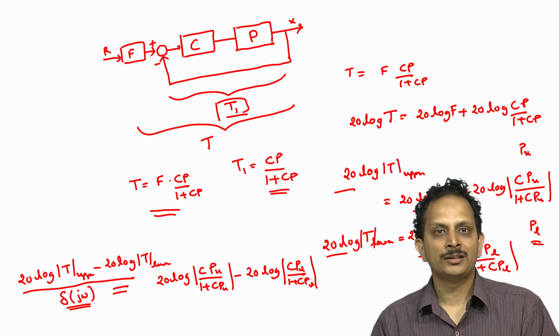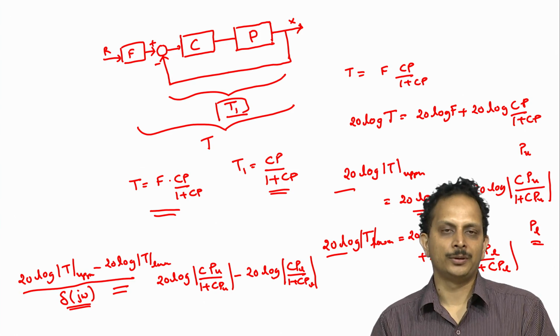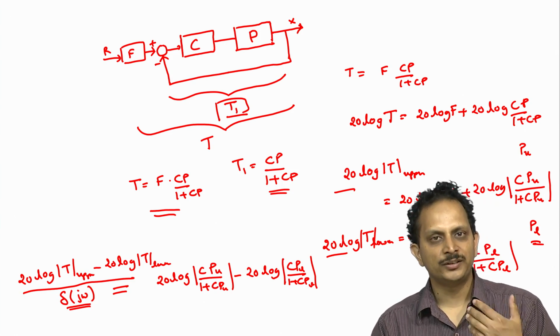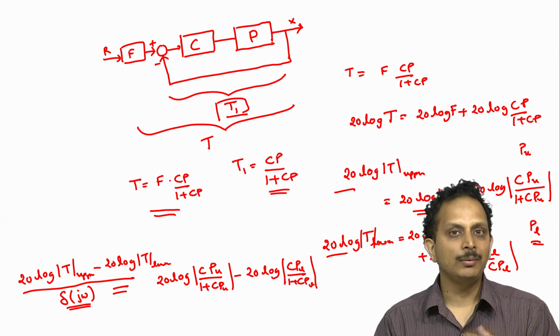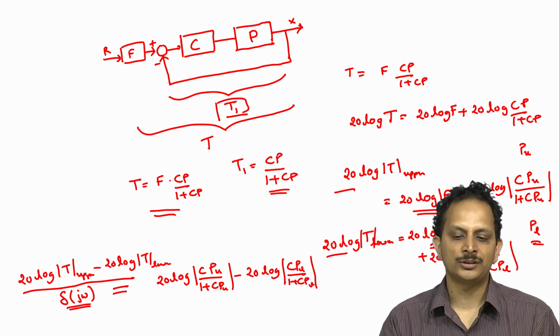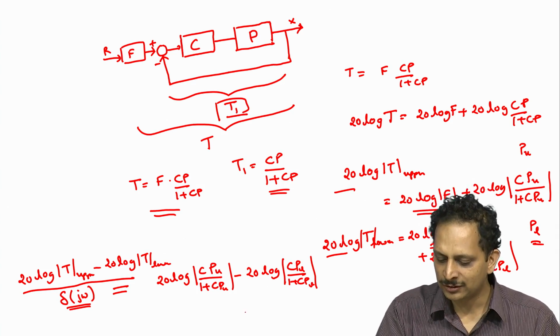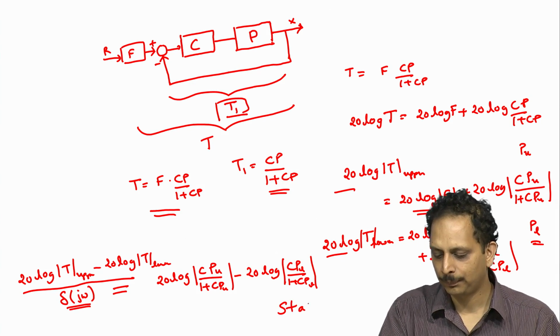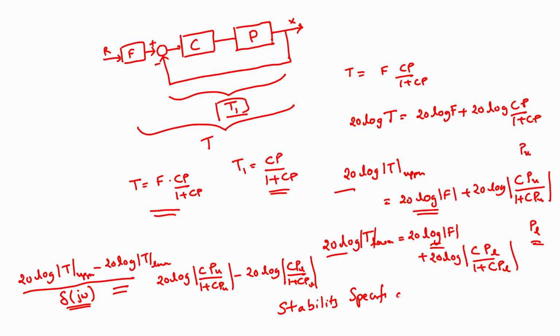So, in keeping with the strategy that we would adopt in the Nichols plot to specify the stability requirement, namely to specify the maximum permissible value for the magnitude of the feedback transmission function T1, we shall add this particular stability specification. Namely that the magnitude of T1 max should be less than or equal to 3.5 dB.